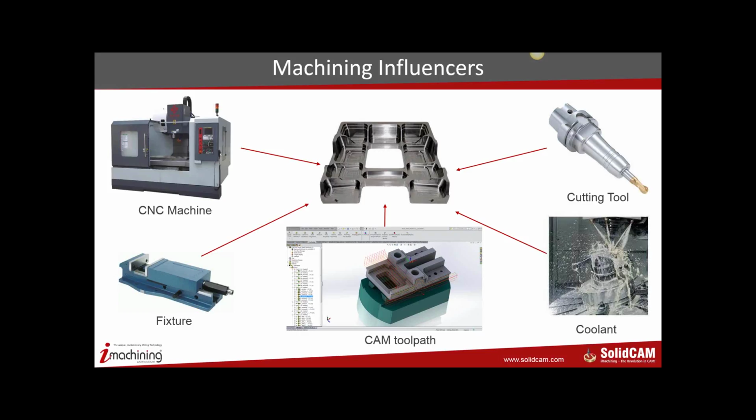The fourth influencer in this case is the cooling itself. The question here is whether to use air, whether to use fluid lubricant. This question will be answered in my subsequent slides, but the important thing here to mention is the design of your cooling will determine how effective your cutting is going to be.